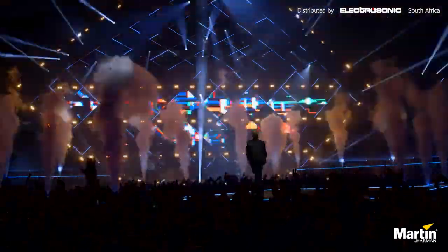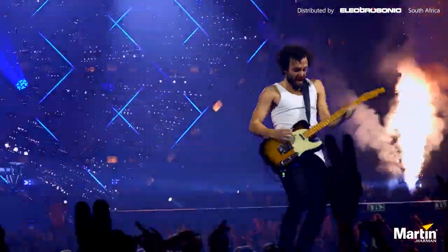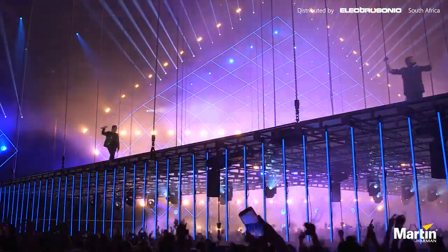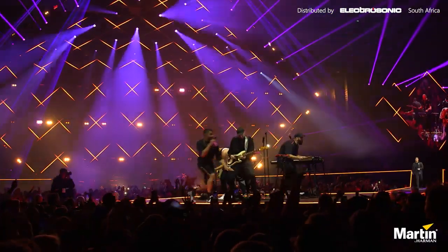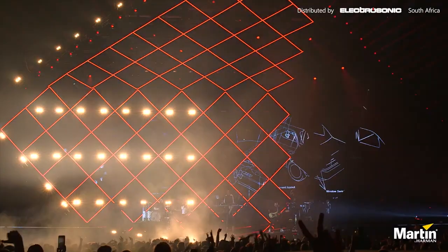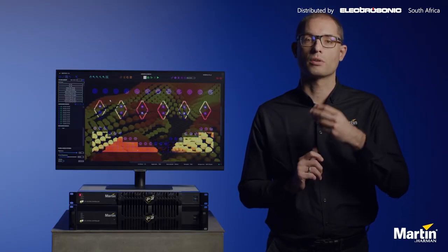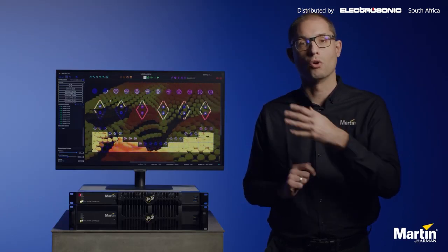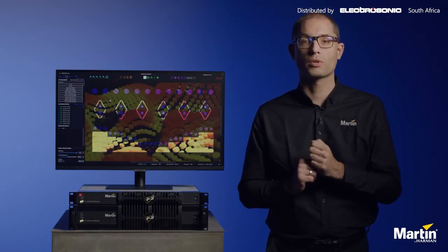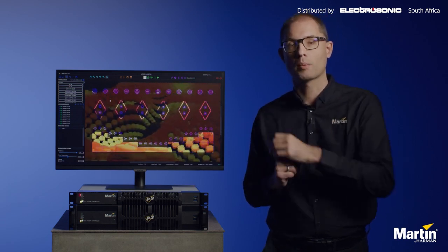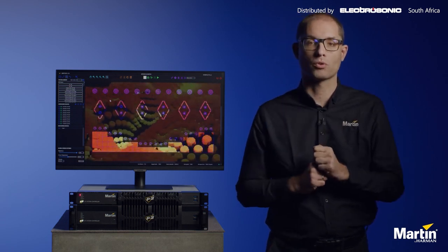For festival and multi-purpose venue applications, the P3 is able to store multiple fixture layouts and DMX patch sets into presets. This makes it possible to change the entire fixture layout and DMX patch in a single click. The P3 also monitors the status of all connected fixtures in real time. This can be seen locally on a monitor connected to the P3 controller or remotely via the internet using the built-in web server in the P3 system controller.